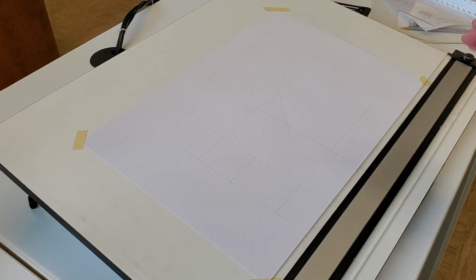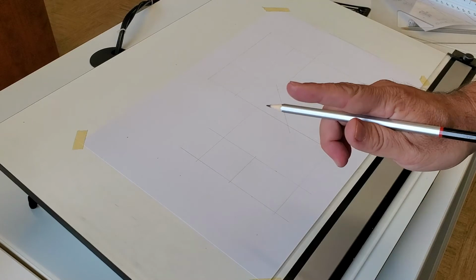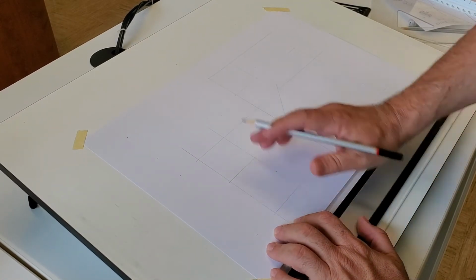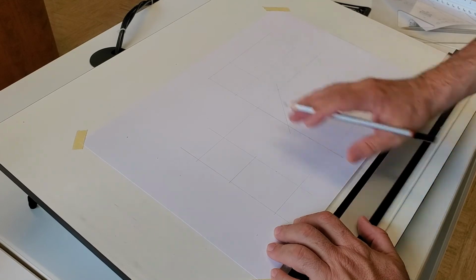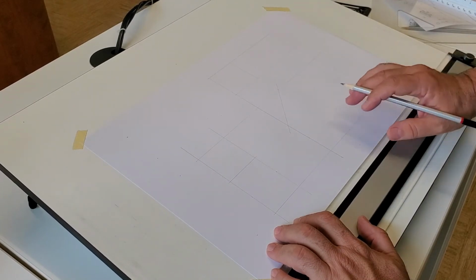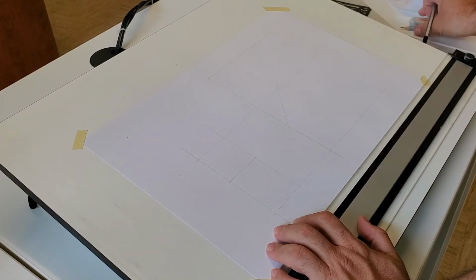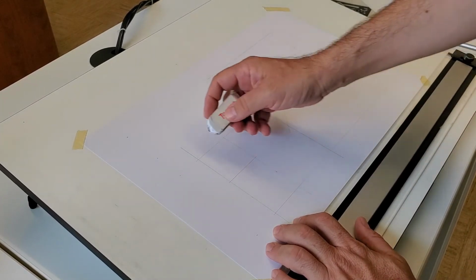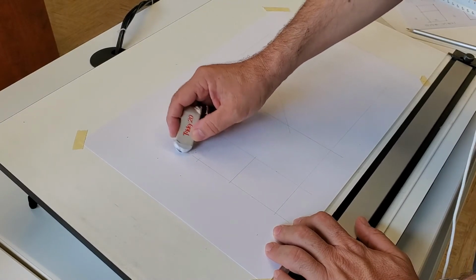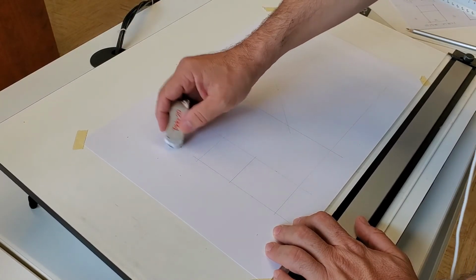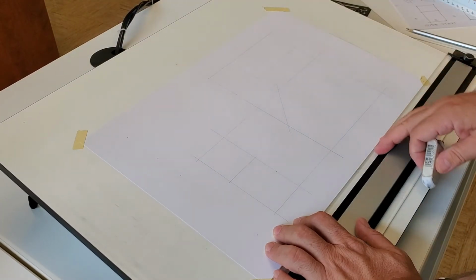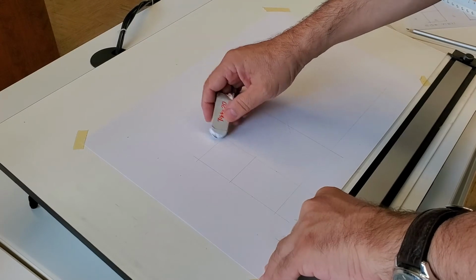Okay. So you should keep in mind that when you are doing projections, ideally you measure only once and then you transfer the dimensions using projections. If you are measuring multiple times the same feature, it means that you are basically wasting your time. Okay? And don't forget that not every time you have very simple objects like this, so you have to do very precise measurements sometimes. So I can a little bit lighten this. I did not erase, just lighten it, lighten this one.